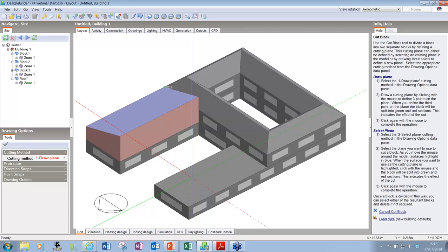Here I'll try to make that roof junction a little less pronounced. By selecting 3 points on the roof surface, I'll trim the first 4 meters off the block. This will create a valley between it and the adjacent sloping roof section.